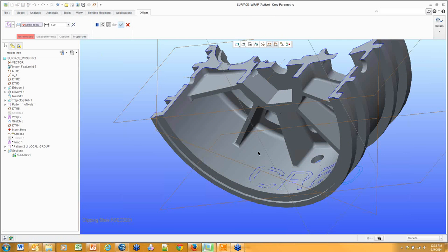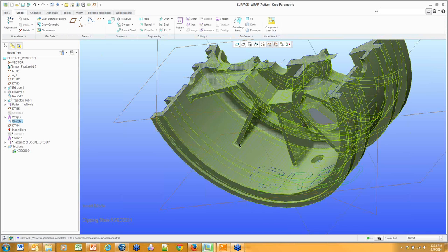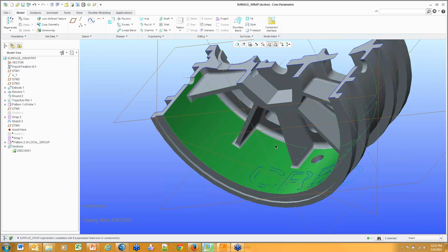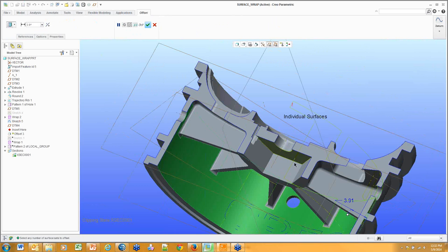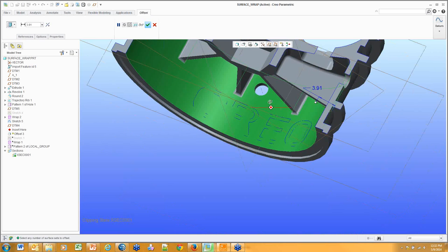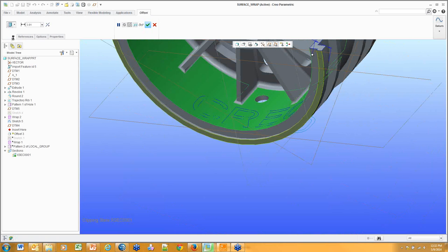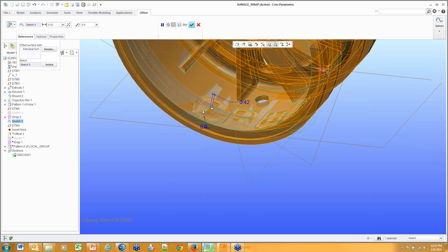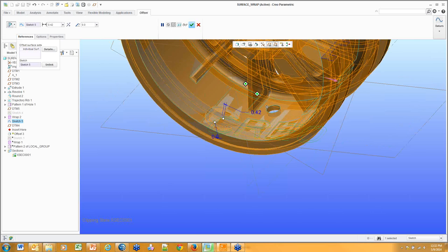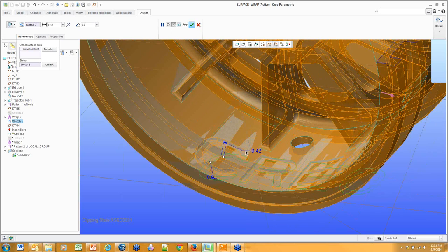Okay, you want to come in here and grab our surfaces. Make sure that you do grab the surfaces on the plane, 1, 2. Okay, offset. We will snag our geometry right there, and it should project it onto the surface. And just to make sure that it is going in the correct direction there. Okay, there we have it.